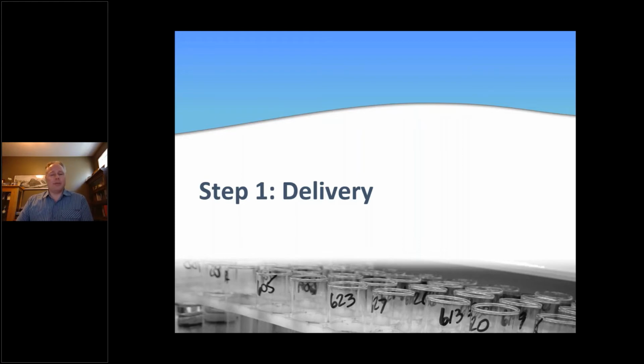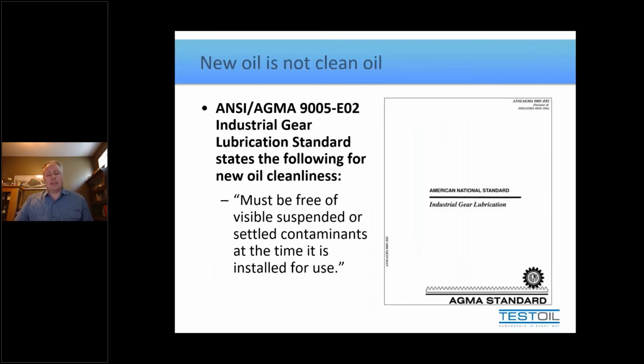And just to show you an example of how we know this to be true, here's a published standard for the required cleanliness for gearboxes. It is one of the most widely cited standards out there, simply because it's one of the few that's published along these lines. If you read what it says about the acceptable limit for cleanliness, it just has to be free of visible or suspended material. Remember, your lower limit of detection is around 40 microns, so you're not seeing the most damaging size particles.